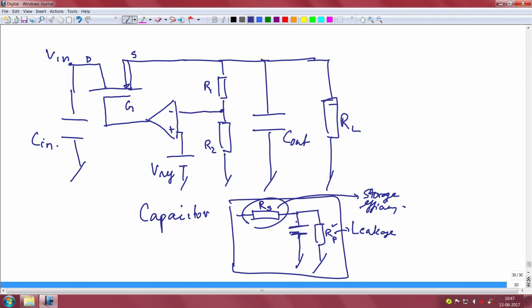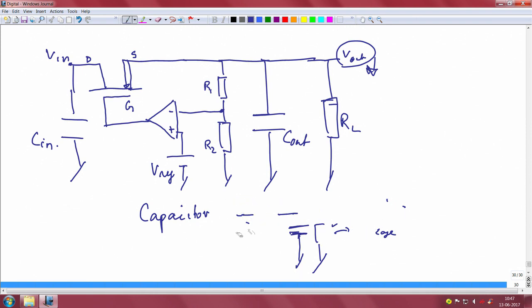So, you have to choose, you are trying to regulate a V out here, and if you choose a capacitor which has a high series resistance, obviously this is going to take a beating, right, because this is exactly what you do not want. You want this V out to be precise, accurate. We gave out all those specifications and you have to actually meet those specifications, right. Let us see what else you can do with that, so essentially what we are saying is that this C out resistor is important.